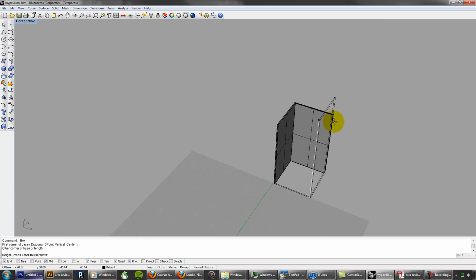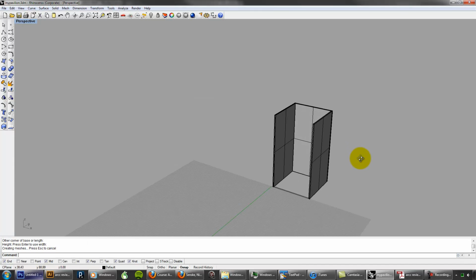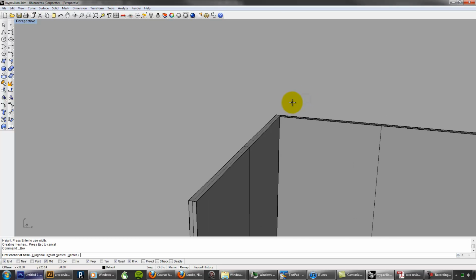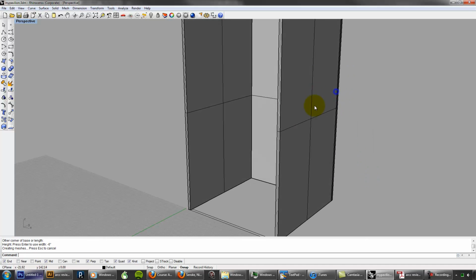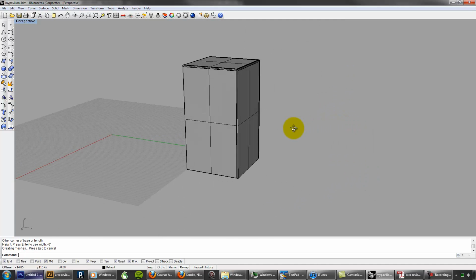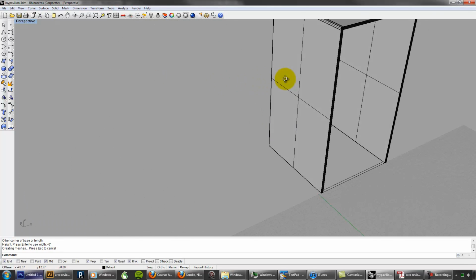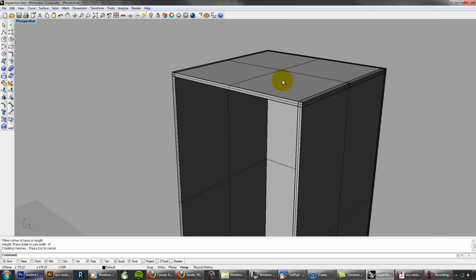And again, this is not great craft, but it does the job. Okay. Then the last piece I would probably do is, I'm going to draw one of these and extrude it. I'm going to set the last thing to be a height of -6 inches, and that gives me a cap for a roof. Not great craft because you can see the seams and everything in it. It's not what I would like to do, but it does the job for the time being.